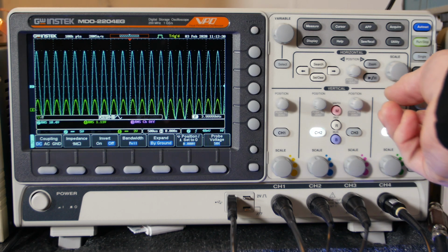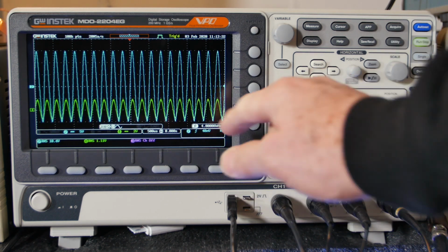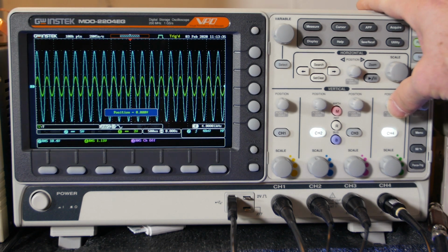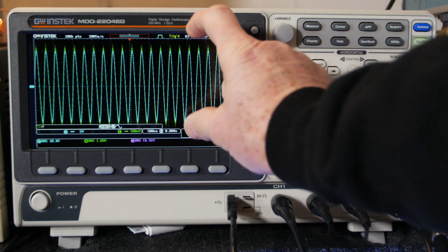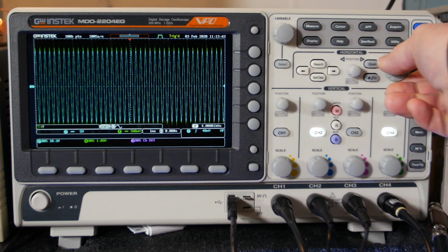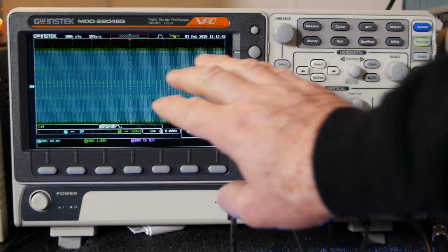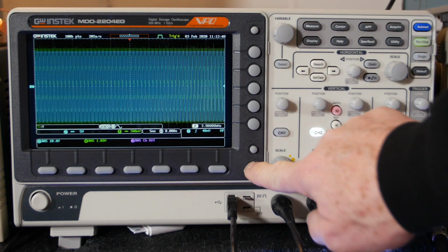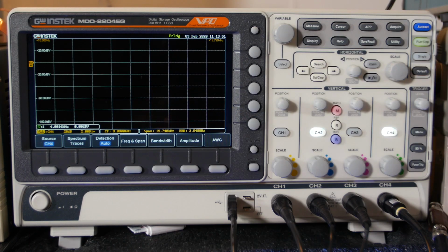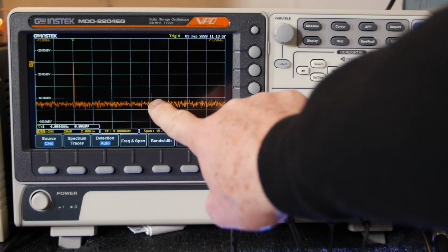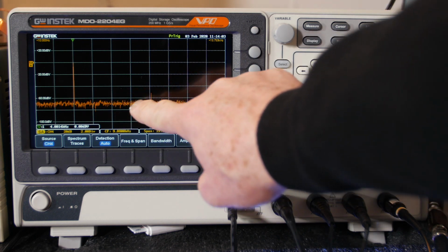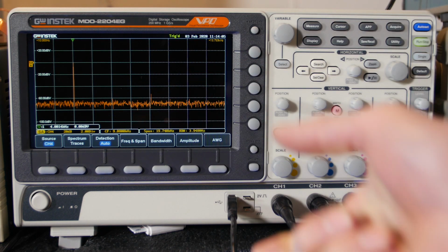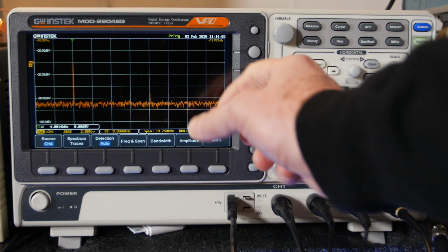If we go back to scope mode, here, let me just push this guy and center it, and I'm going to amplify it, bring it up a little bit so we can see more of the waveform. And I'm going to capture more waveforms. I don't know if that makes a difference. Let's go look. Yeah, I think that did kind of, look at that. I still see a little spike here. It's smaller, and so, you know what? The signal to noise ratio, because I didn't have enough amplitude.